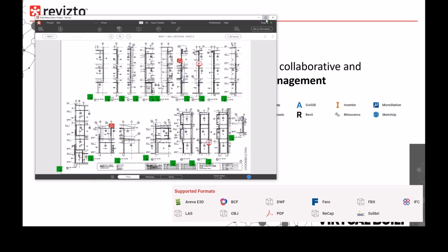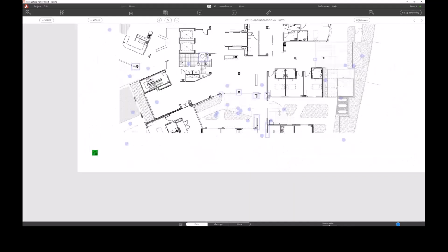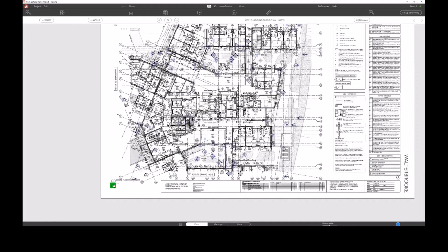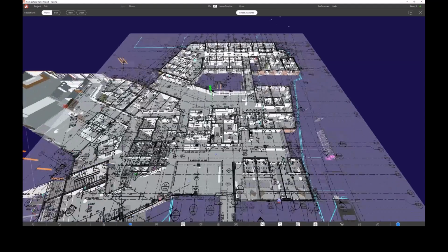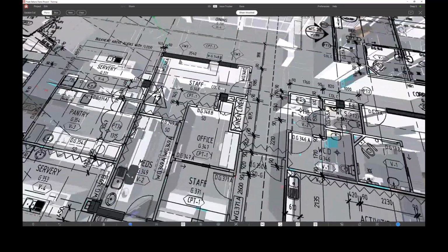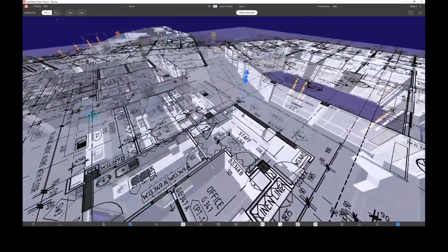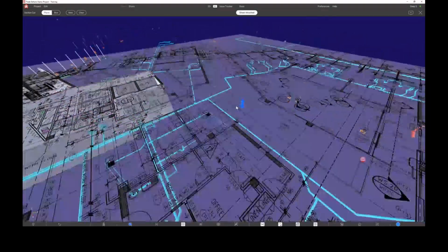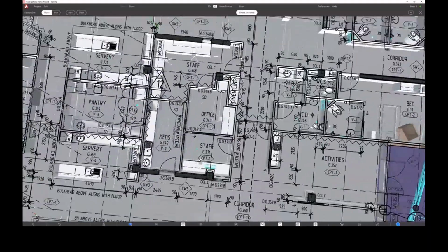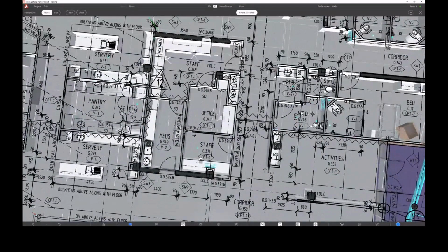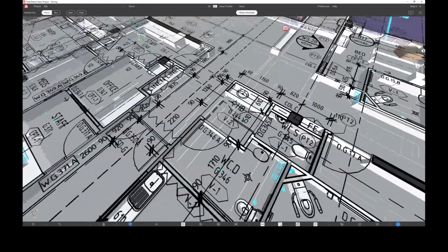So looking at the 2D side again, we've had a look at a section view overlay there, but we could take this entire floor plate and click the same scissors icon, and we're now overlaying the architectural drawing for the entire site there, and we can have a look at how it relates to the in-ceiling space, to the subfloor, and we can see all of the relationships. And what we're really looking for is things the architect might have missed or maybe not gotten right.